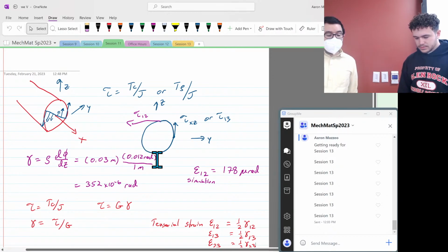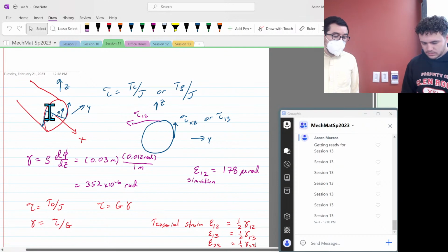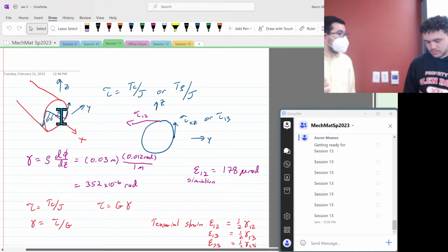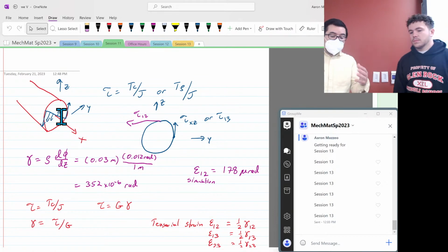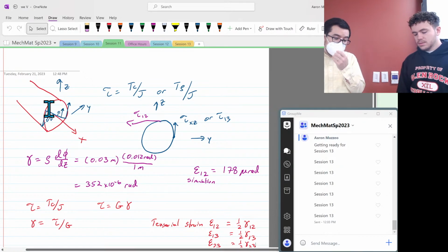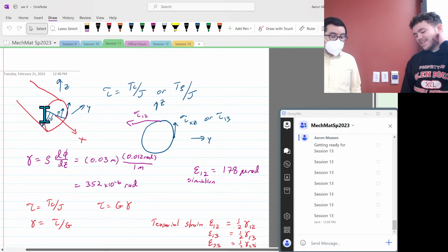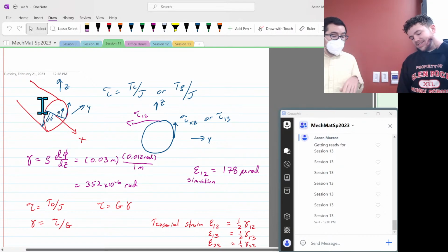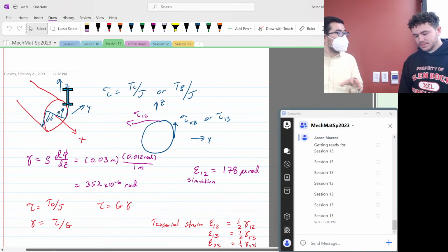Now the other thing that can happen is that we decide to take the stresses right on this open face, like for this model. That can be a little bit dangerous. There's something called the Saint Venant principle, which says that you need to be a little bit away from where the loads or the constraints are applied in order to get these ideal approximations. So in addition to not taking a node on this face, there can be some anomalies there. You want to take a node like over here or over here, a little bit down away, okay?